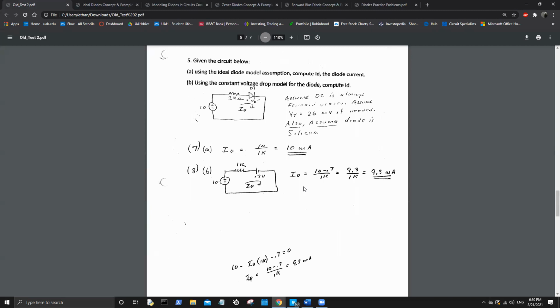Then I would calculate. What I'm planning on doing is using 0.7 if he doesn't specify one, and then if that math doesn't check out, I'll do 0.6, assuming my math was right. Wait, 0.66 is what he's been saying? No, 0.6. That sounds suspiciously like a germanium diode voltage drop.